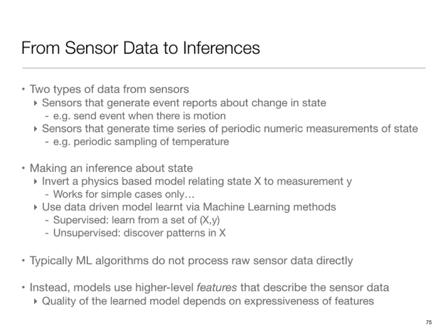And events are basically change of state. Essentially, we monitor that underlying time series, and whenever we see a change, we send out a report. So instead of saying dark, dark, dark, dark, light, light, light, light, dark, dark, we'll say dark to light transition at time t1, light to dark transition at time t2. So we basically send out reports when a change in the measurement value happens.